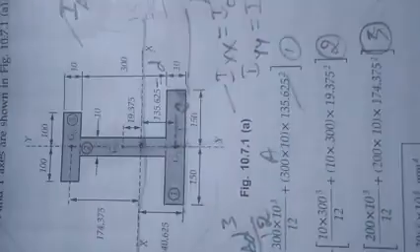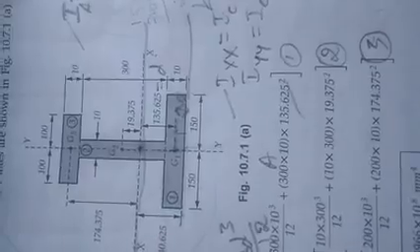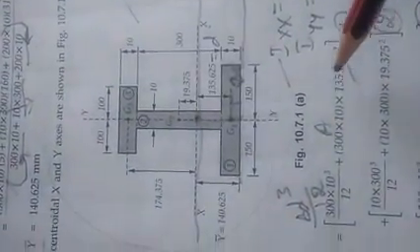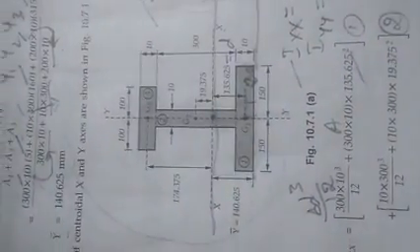I will show it in a very clean figure. So what you have to do is find out the y now. How to find y from this whole section? You already know how to take the I value and A value. Only you have a problem with this D. So how do you find the D of each individual section to the reference axis? I told you how you got this 135.625, but I will tell you with a clear example.